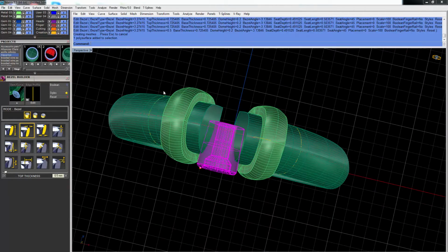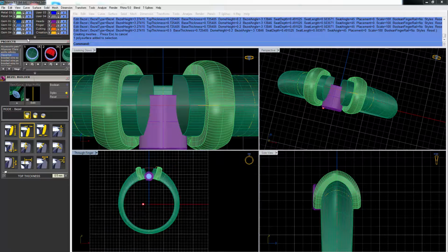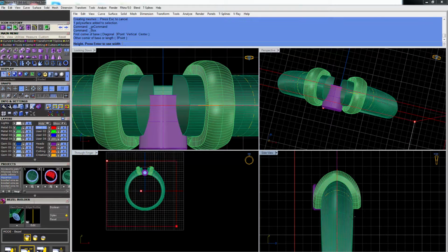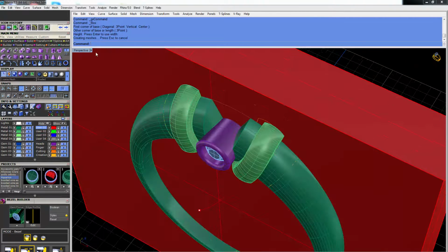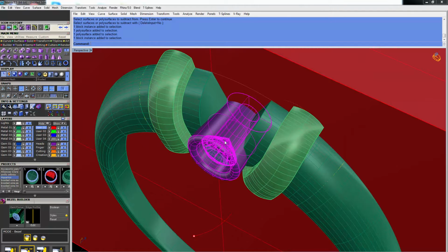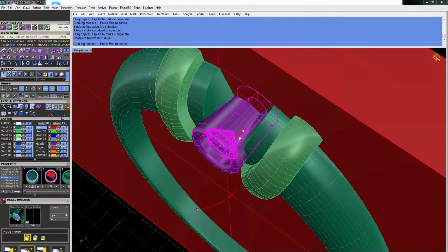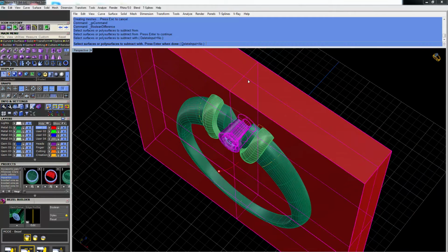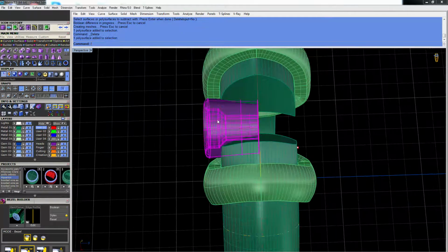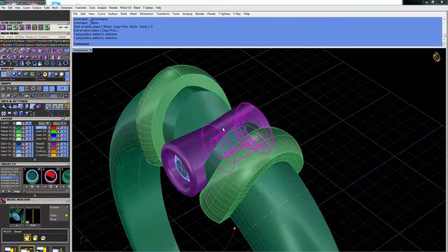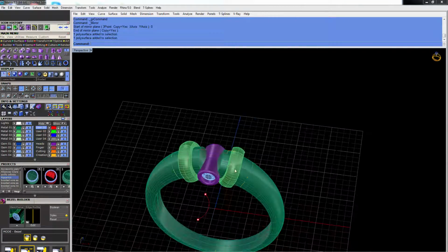Okay, now we need to split this, so we can just easily go to solid, make a massive box that way. So now we can just make a boolean difference from this object. Hang on, I'm going to put it slightly inside, maybe not that much, something like that. And now boolean difference from this object and this object. Okay, I did this because now I can select these objects and make a mirror from there to there. Okay, and it joins exactly in there. Okay, so we have a neat finish up there.